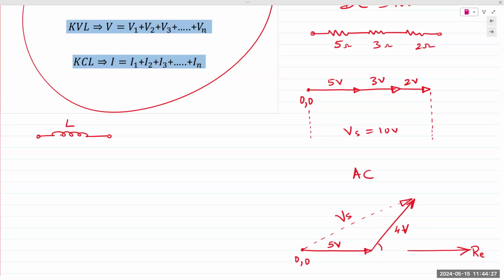An inductor is simply made out of a conducting coil of wire. You take a conducting piece of wire and you wind it up in a spiral coil. That coil can be very tightly wound, so the length of that wire when stretched out will be very, very long. Even a tiny inductor this size would be very long in terms of length. If you remember chapter 3, inductance L is directly proportional to the number of turns in the wire. Remember, the higher the number of turns, the higher the value of the inductance. However, that has a drawback.